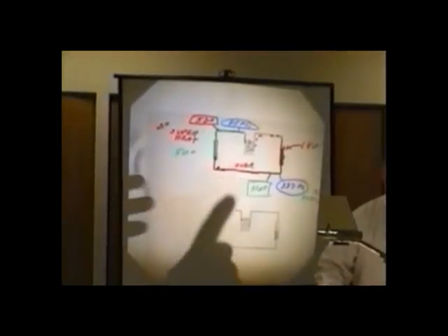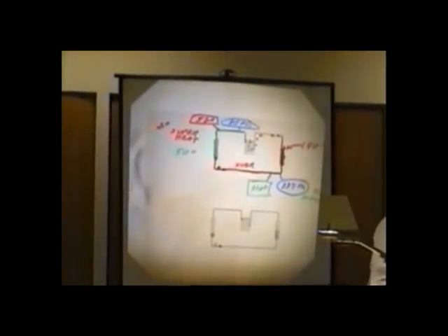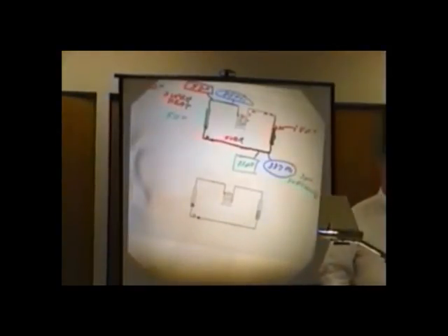Ready? We're getting to the good stuff here. What is normal superheat again? Superheat's all over the board, depending on conditions. That changes. But all we're trying to do is give you an example of a 95-degree day, normal. Let's go back, and then I'll go back again. But overcharge, subcooling goes up, and superheat goes down.